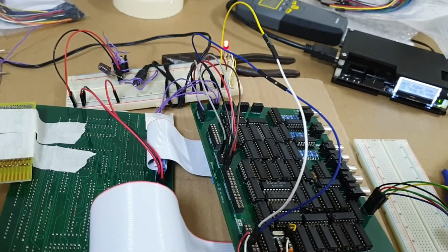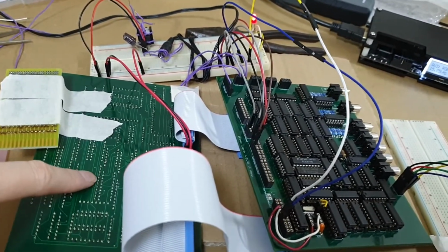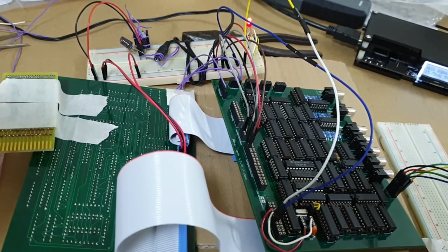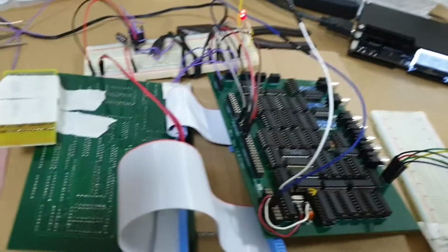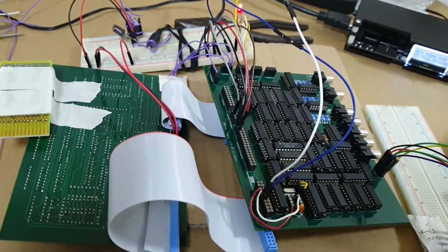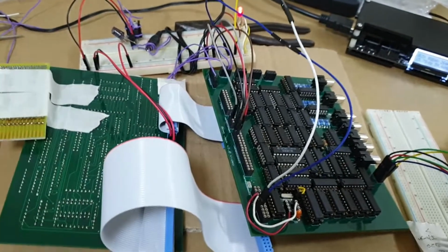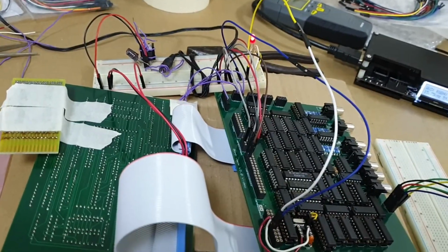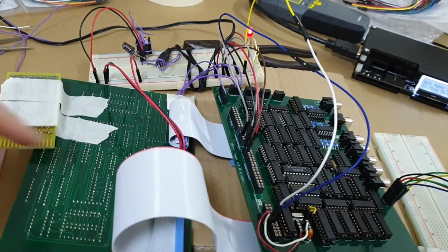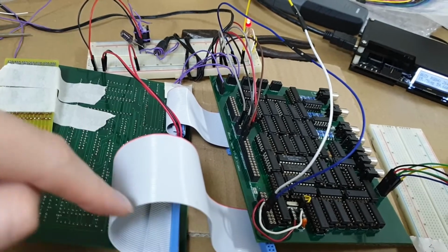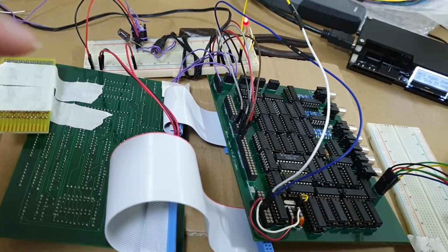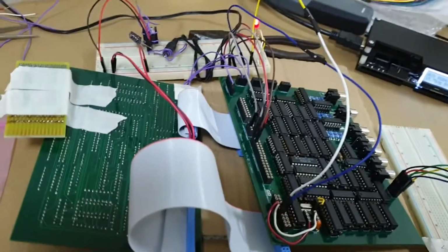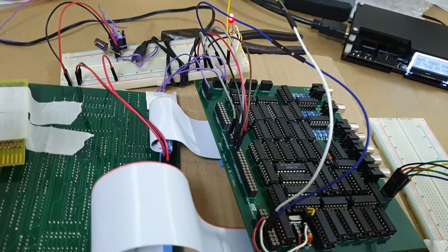I would really love to learn more about this, because this is not going to stop at this character board. There is a sprite board. There is a 16 by 16 pixel tiles board. There is the huge, ginormously large in comparison, Mode 7 board, which I want to try and get working. I think I'm going to have to start thinking about much beefier power for this, right? In theory. And these are 6-layer boards, and I've put links to the Gerber files, the Proteus files and everything else, so it's all open source, so everyone can see exactly what is there, how the layers were stacked up. I'm really quite happy that it's working to this extent.